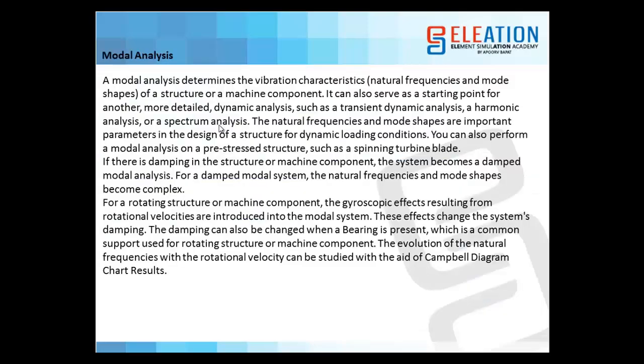Now one more thing which we are going to cover on the part of analysis is modal analysis on the roll cage structure. So we mostly perform modal analysis to find different mode shapes generated because of the frequencies, which are generated because of, say, engine frequencies or road frequencies or atmospheric frequencies because of the motion. So we calculate this frequency range, and we see how my component will behave in these frequency ranges.